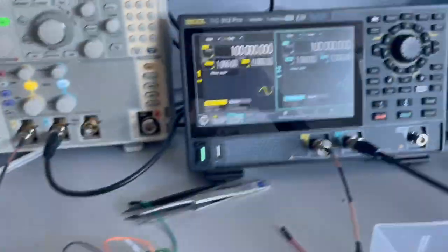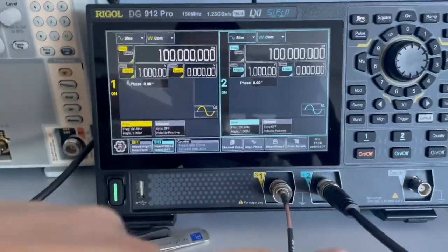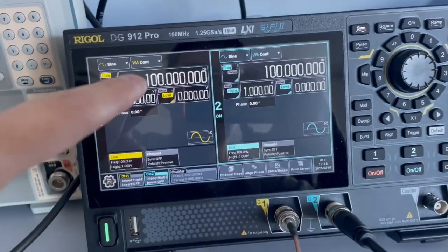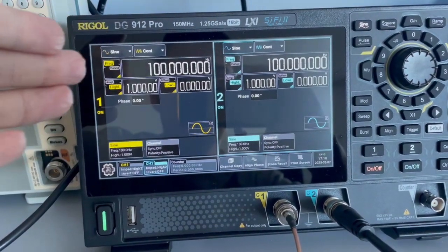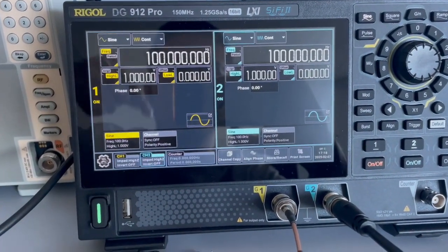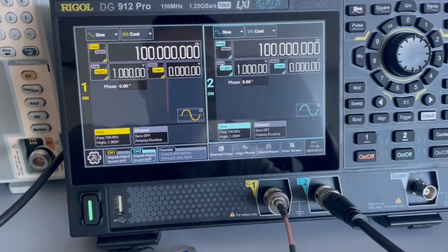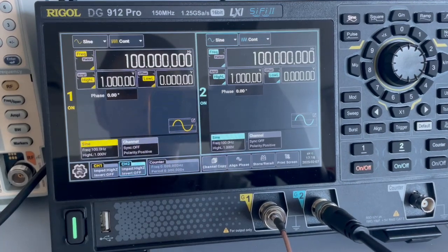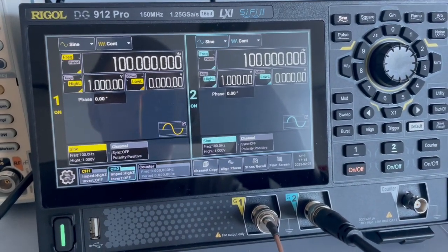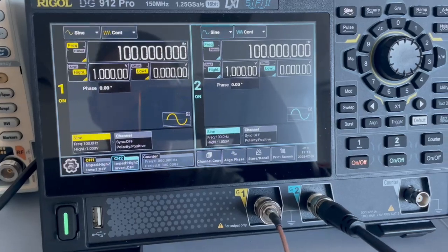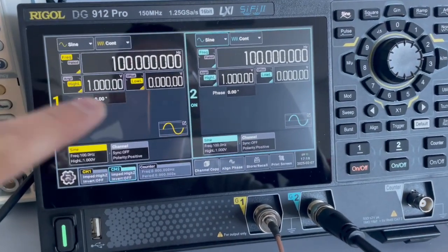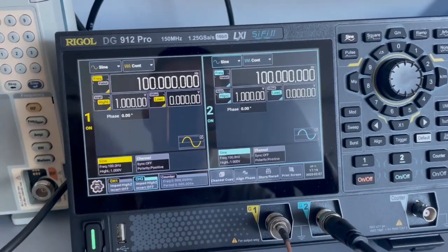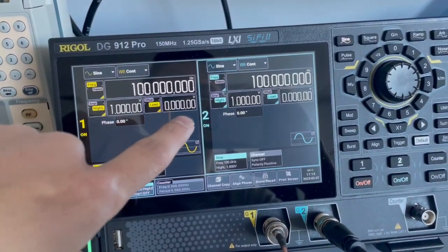Basically what you have to do, you have to set a signal generator, connect two BNC cables to compare input and output, set your signal generator to 100 Hz, and this time make sure that you don't have negative signal, since diode doesn't work well with the negative part, so it's just gonna distort the signal and doesn't allow to pass the negative part. So make sure that your signal is from 0 to 1, not like previously where the signal was from negative to plus.